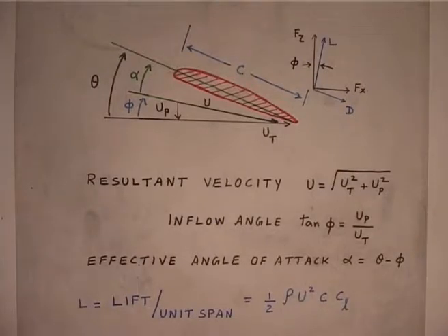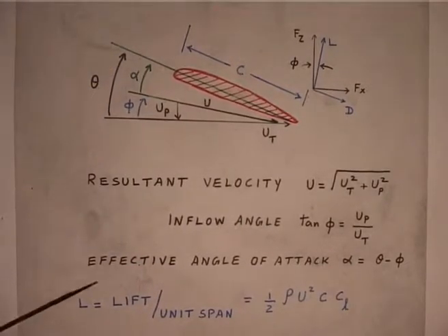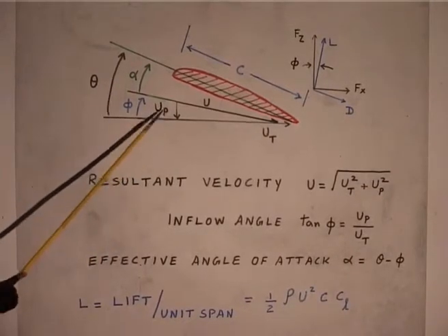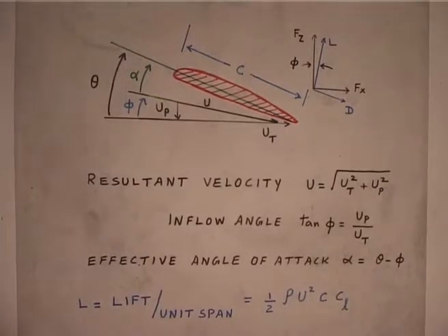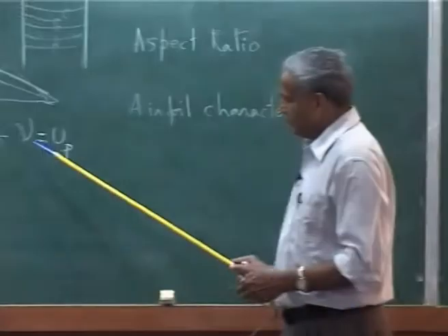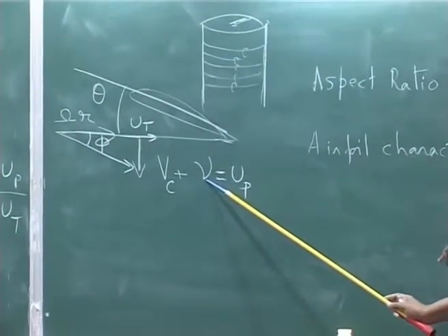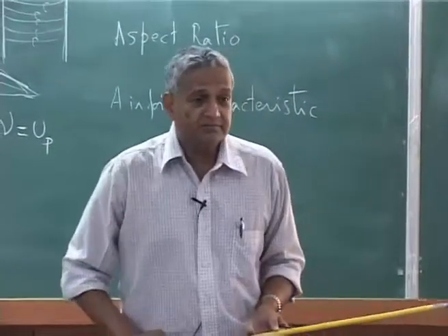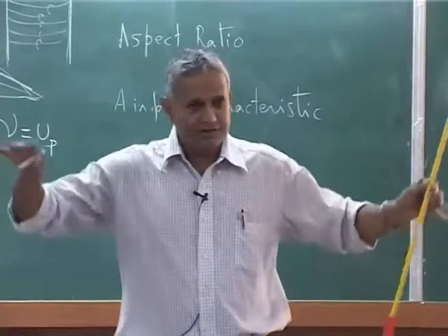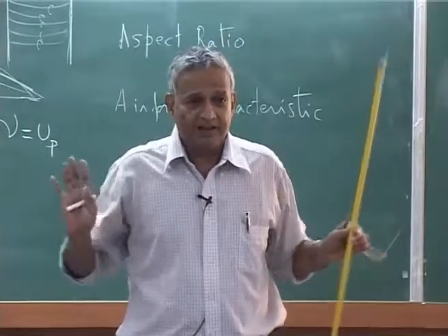He gives only pitch change, in the sense he changes this angle, but the angle of attack changes depending on what is the up, what is the ut, etc. I may assume now this induced velocity nu to be constant over the rotor disc, that is, it is not a function of r, it is a hovering or climb theory, it is not a function of radius, it is a constant.